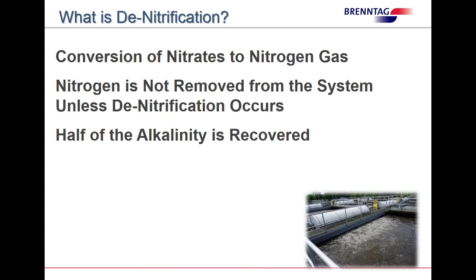Okay, let's talk about denitrification for a little bit. Denitrification is a conversion of nitrates to nitrogen gas. Now, nitrogen is not removed from the system unless denitrification occurs. So we need to get those sizzle type of bubbles coming up in your clarifier or your system.